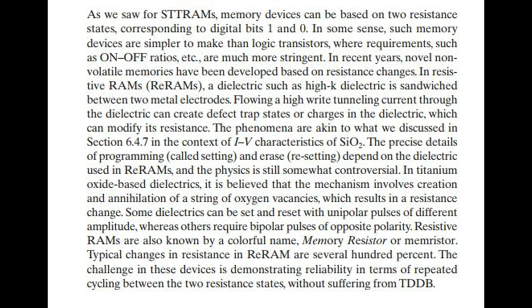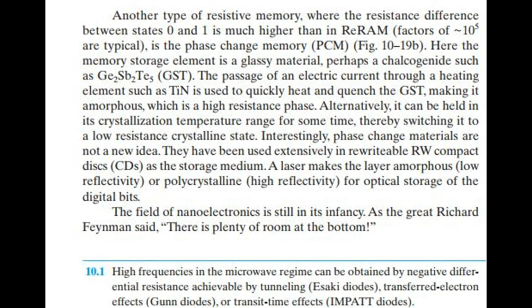Resistive RAMs are also known by a colorful name, memory resistor or memristor. Typical changes in resistance in ReRAM are several 100%. The challenge in these devices is demonstrating reliability in terms of repeated cycling between the two resistance states, without suffering from TDDB.